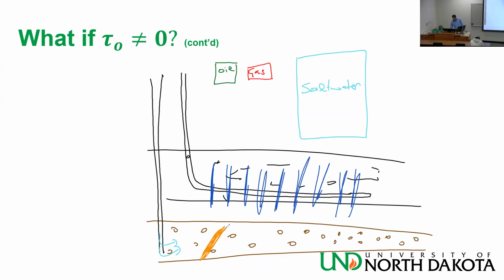I increase the pore pressure, and then I find a fault there that is ideally oriented, and the pressure goes up, it exceeds the Mohr-Coulomb failure criterion, and I have failure. So I have this Mohr circle, and now I don't need to have an intercept because tau naught is equal to 0.